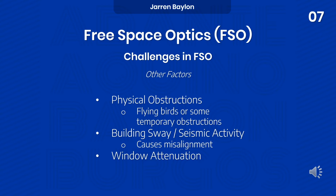Usually, building sway is not more than 4 to 10 milliradians, but such a small misalignment can also increase bit error rate. In such situations, beam divergence is kept larger than expected building motion. Automatic pointing and tracking is the best option for exploiting optimum performance of an FSO system.